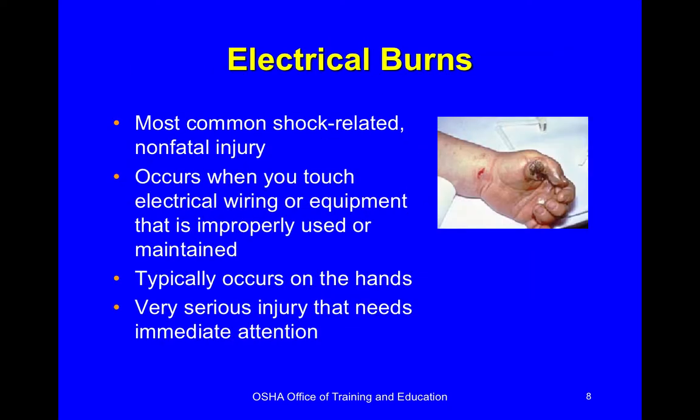Electrical burns, this is very common. Typically they're non-fatal, although they can be bad enough that they could be fatal. Again, they're going to occur typically where you touch the energized device and where the electricity exits your body. Again, typically a foot. But if you're touching two different things with your hands and the potential difference is there, they'll both probably be in your hands. Keep in mind, this is going to be also baking the inside of the hand as well, wherever that current is flowing.